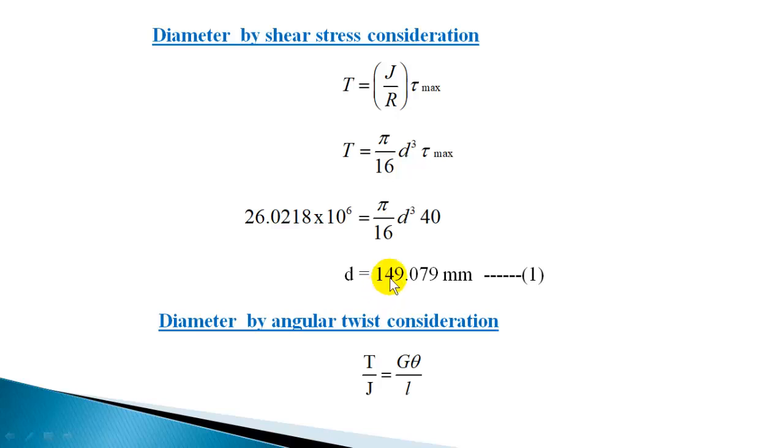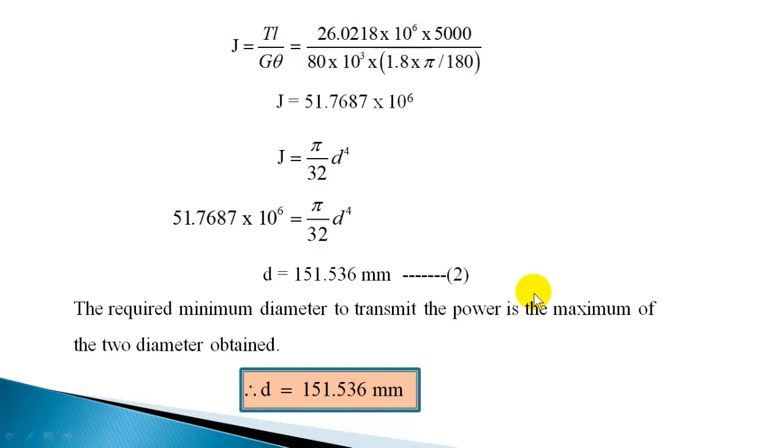It can be more than 149.079, but if you increase it, the shear stress will decrease, since for this torque, increasing the diameter only decreases the shear stress.